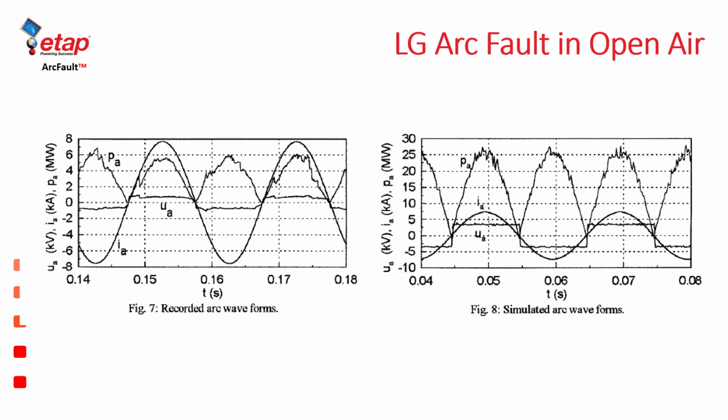After you have the opportunity to watch some of those videos and get some of the physical background of how they behave, you can look at the end results of performing these tests. The end result is to capture the waveforms of the arc current and arc voltage as they occur throughout the arc duration.